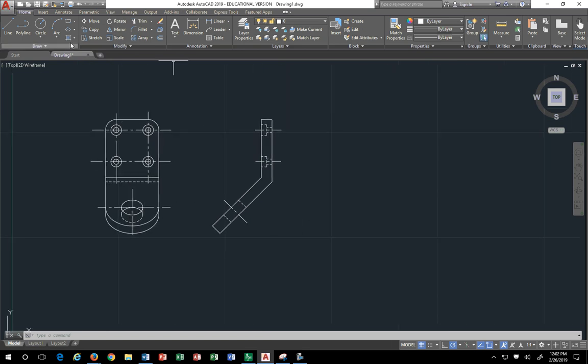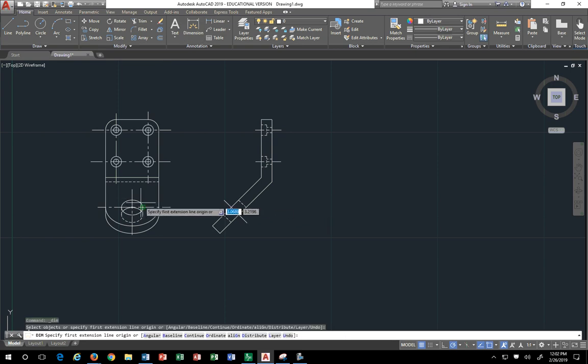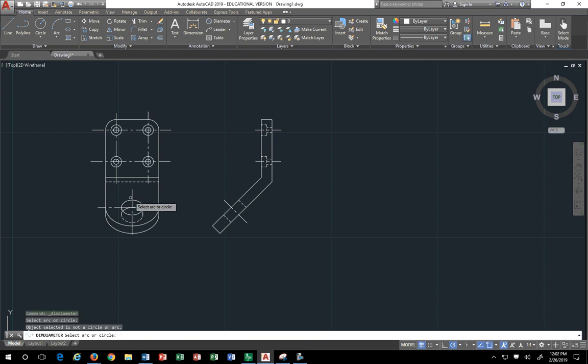Because for all the dimensioning that you're going to do, you will never, ever be able to dimension this object. Meaning, you'll never get the diameter of this object. Why? Because it's not a diameter. You'll never get the diameter of these objects. They're not diameters, they're ellipses. Ellipses are not round, so therefore they have no diameter. They have actually like 3 diameters at least. 3 different diameters that they're using to develop an ellipse.